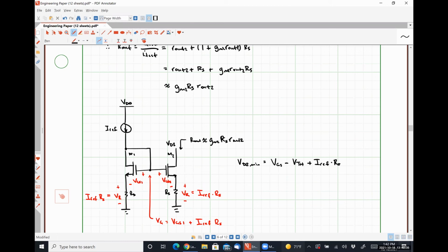So if we're assuming that VDD is the highest voltage that we have in our circuit, what that means is that we've increased our output resistance by decreasing what we call headroom, which is the size of signals that we can apply to things, okay? So in some instances where we're amplifying maybe very, very small signals, it doesn't matter too much. But if we're trying to amplify larger signals, this completely breaks everything, right?